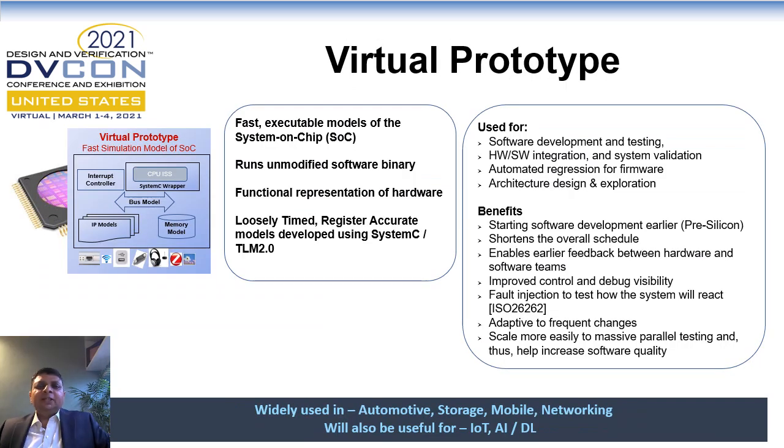One of the most widely used applications of ESL is virtual prototyping. Virtual prototypes are fast simulation models of the SoC or the complete system, and on top of these models we can run exactly the same software which we are supposed to run on the real hardware. These are register accurate functional representations of the hardware, developed using SystemC and TLM 2.0 and advanced modeling concepts like loosely timed, temporal decoupling, etc.